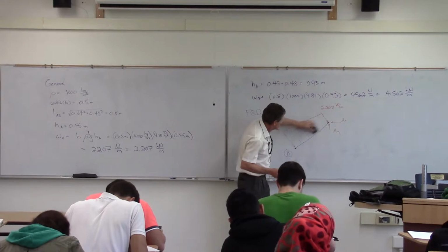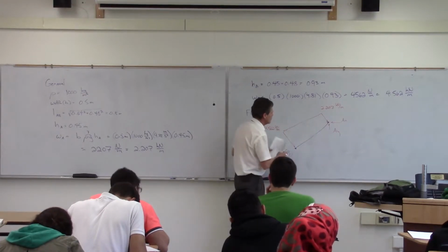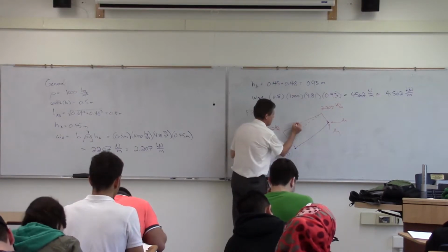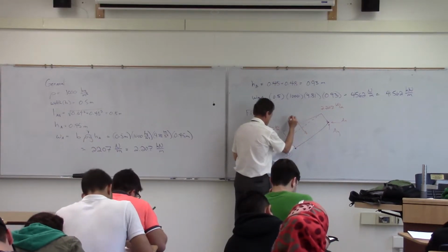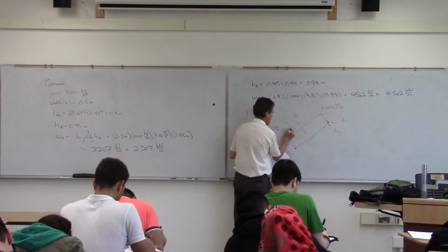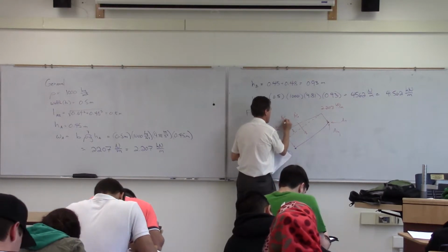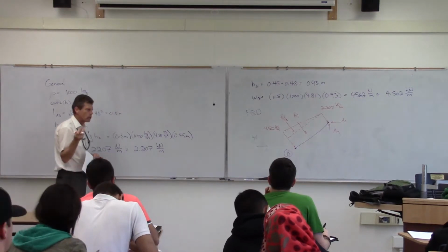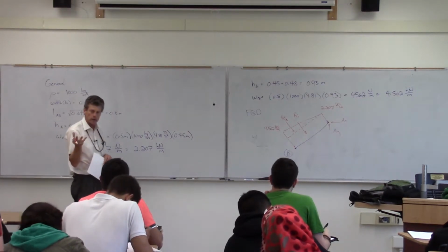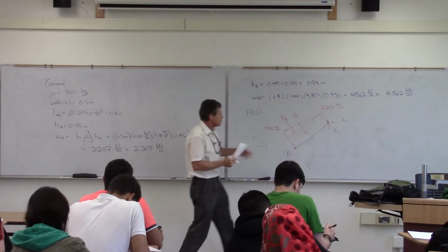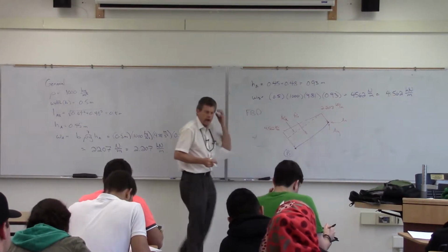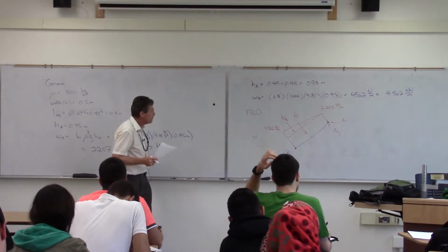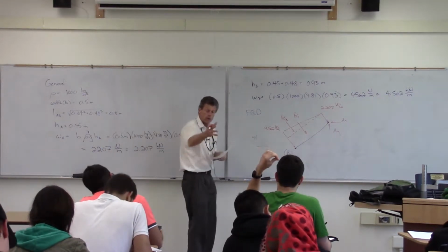We're going to do our equivalent load scheme there. I'm going to create equivalent loads to those two particular load areas. In this particular case, the rectangular and the triangular. Again, your author uses two triangles. Either one's fine. I don't like dividing by 3 2 times, but whatever works. And actually, it's a good way of checking your work.